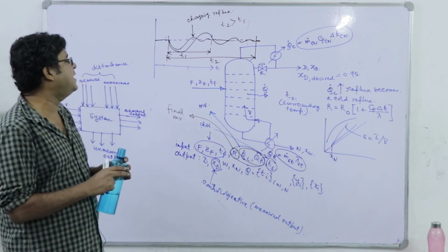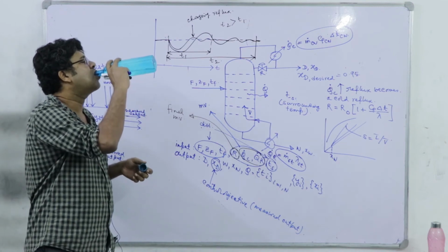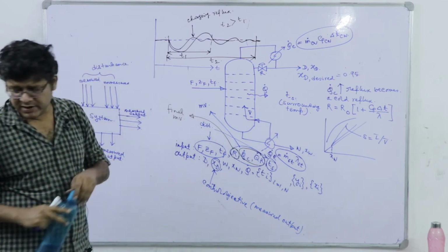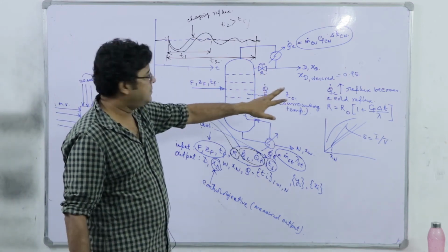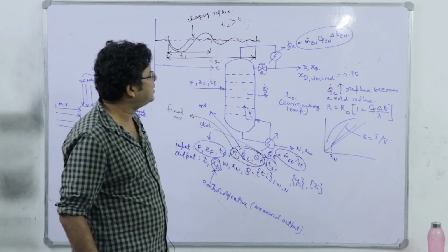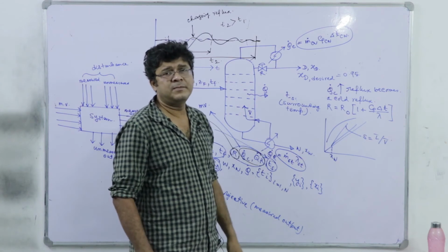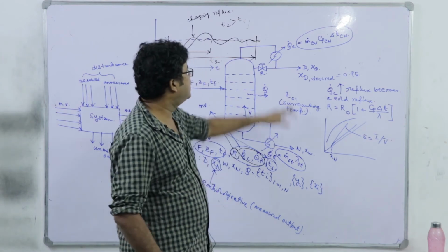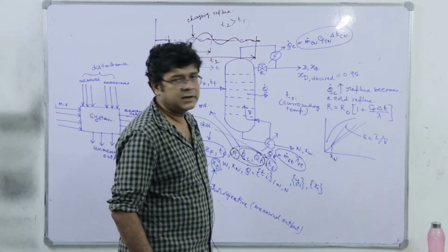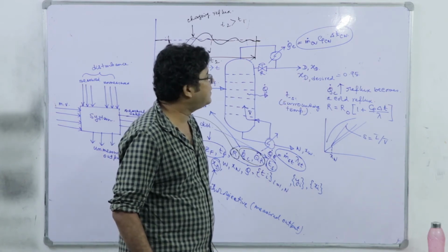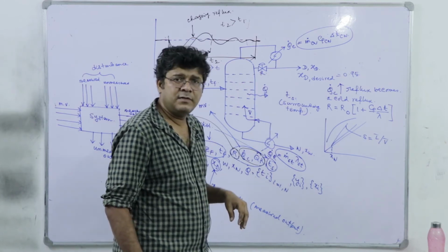So what is the easiest control strategy or configuration we can implement here? Definitely think manually first. Say we are thinking of possibilities of manual control. So I have to go on measuring this XT continuously, right. So once we get that, okay, it is deviating from the design value, and that is the desired value, which is 0.95, I will go on adjusting the valve.